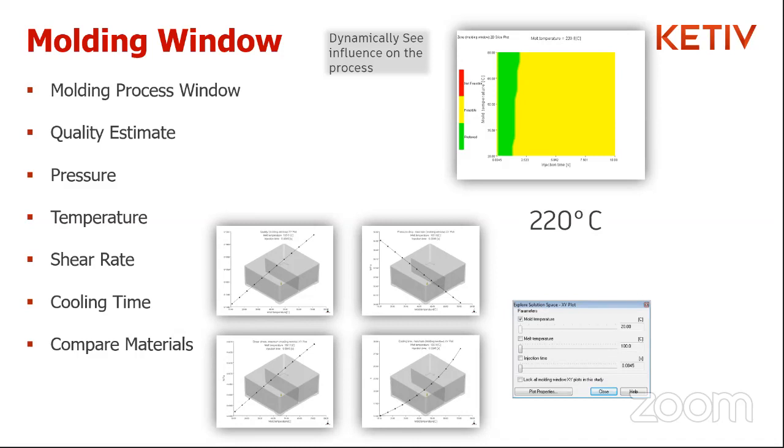If you're building a structural component, for example, it doesn't need to be 10 times the weight it's supposed to be, even though that is technically going to be safe. You actually want it to be as close to safe as possible, or beyond safe, but as close to safe as possible. And this is quite similar, right? You don't want the temperature to be running up too high. So you say, well, okay, I'm going to analyze this at 180 degrees Celsius. So at 180 degrees Celsius, it looks like it's just on the edge there.